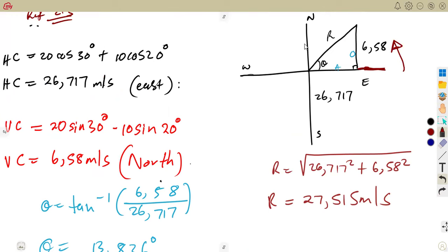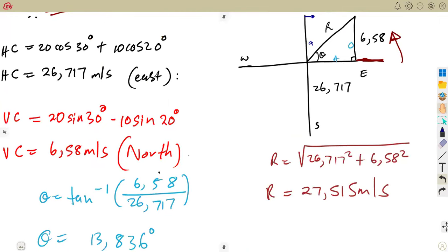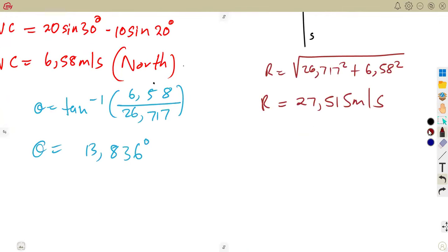Moving from where, as we are considering this quadrant, from east, this is the line going from east to north. Or you can take this one from north going to east. So it will be north, and you use this angle alpha if you want to take that angle alpha. So it will be north alpha degrees to the east. But you must calculate that. In our case, guys, we calculated theta. So we're going to use that, east to the north.